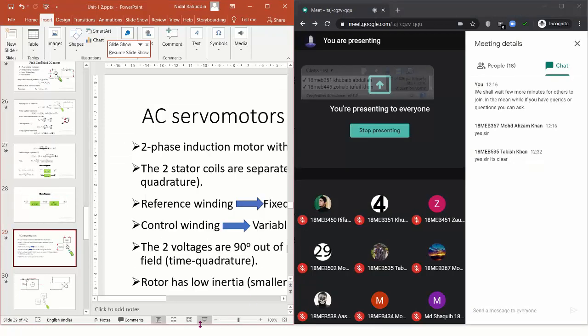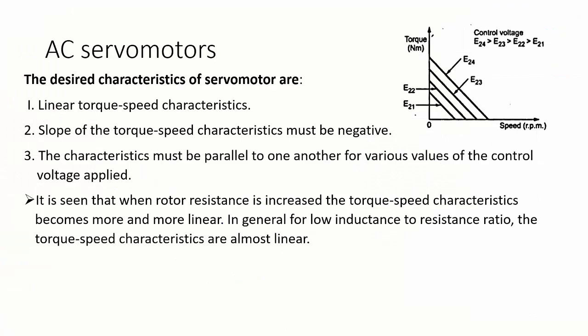One thing I should tell you about the AC servo motor is that you can obtain the torque expression for it, but it's difficult, because the torque-speed characteristic for the AC servo motor is not exactly linear. Since we have a slight arc-shaped characteristic, instead of applying the conventional method to obtain the torque relation, we take the curve, apply a Taylor series, and obtain an approximate expression that fits the curve.